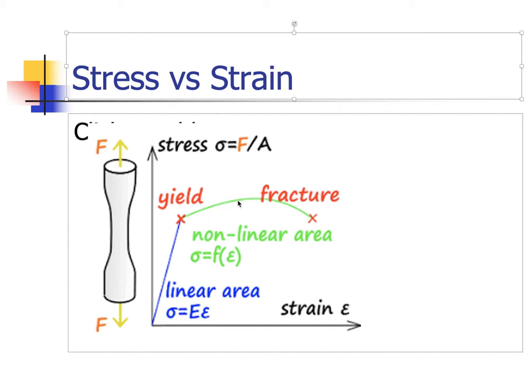And what's going on here, it's cold working a little bit, and it's getting smaller in diameter. As you stretch the thing out, it gets smaller in diameter. So theoretically, we should actually have to recalculate this whole stress thing. But because we're kind of lazy and we're just trying to get an idea of what's going on, we don't do that. So the metal looks like it's getting stronger for a while, and then it's getting weaker. It's always cold working, but what's happening here is the diameter is getting so small that it eventually breaks.